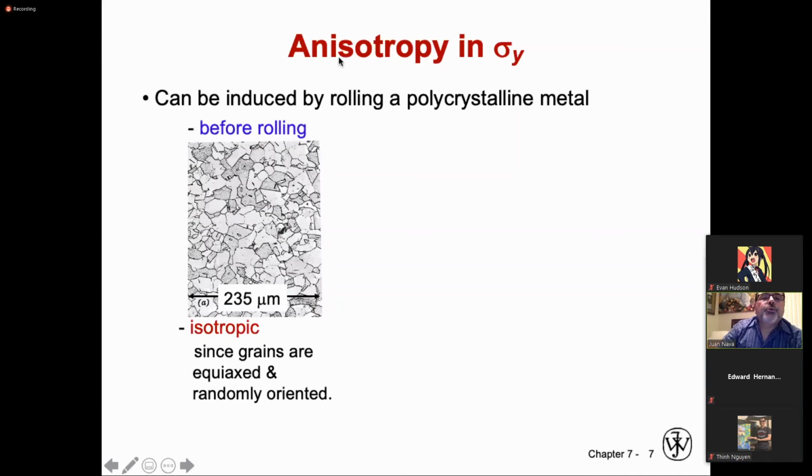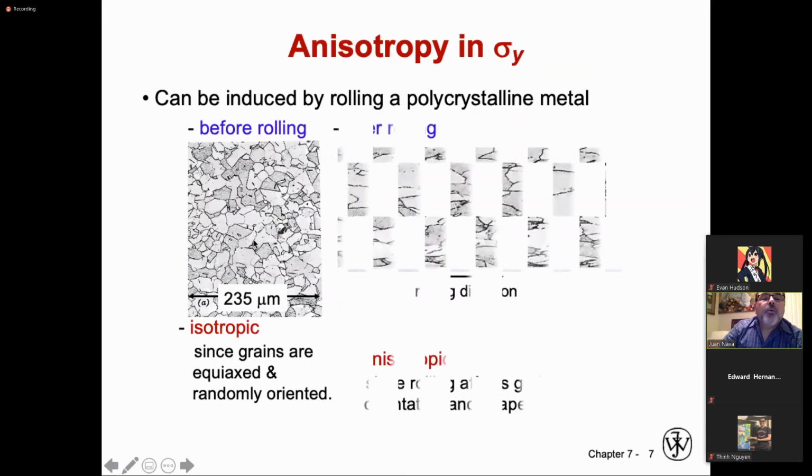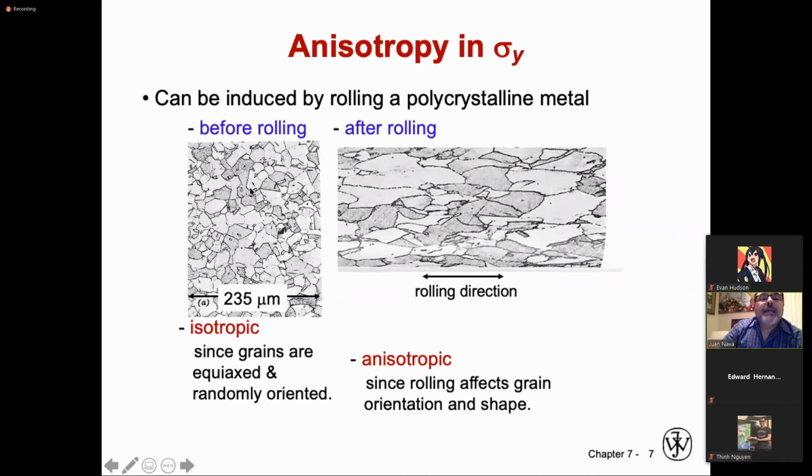So when you do strain hardening, you begin with a homogeneous distribution of grain structure. When you are done with that, those grains have been elongated in the direction of the cold working process. This is what is going to get you that strengthening.